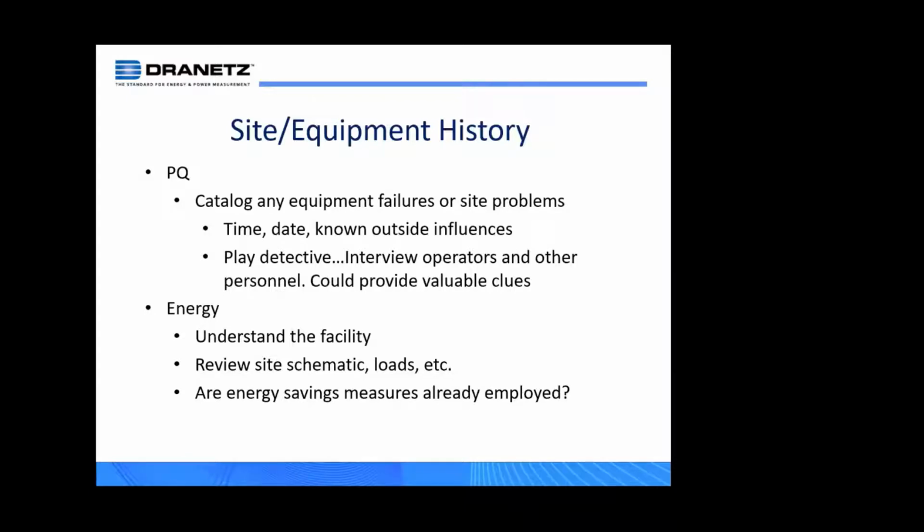If I know that every time the lights flicker, the instrumentation that I'm using to collect the data identifies an event, and I have that consistent correlation, well, then there's a very good chance that that is the source of the problem. So that's the first place that you begin in order to mitigate the problem. So a lot of times, most of the time, you'll play detective. You'll interview operators. When did the VFD trip offline?